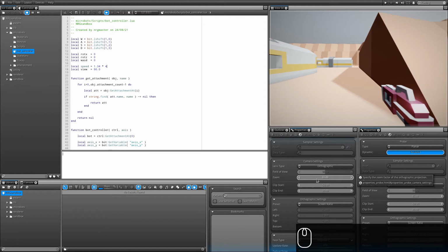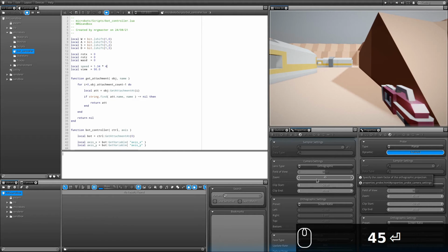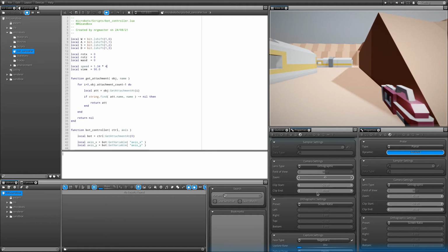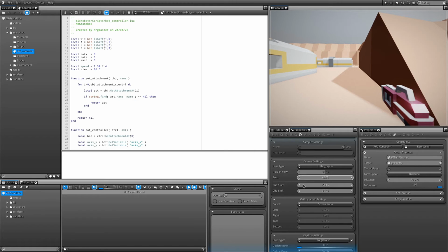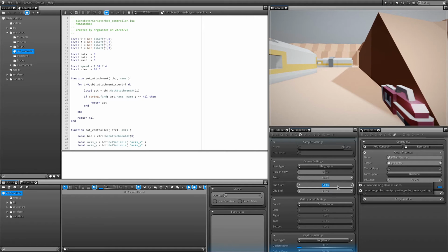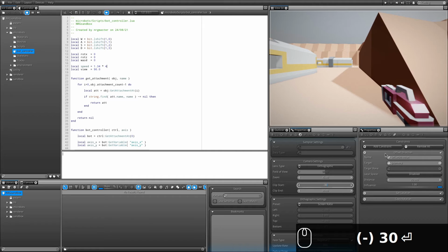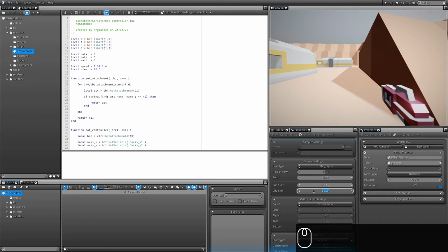Here I am going to set for my first probe that the zoom is at 45. And I go around and simply tweak and try to find the best combination. And here I am going to pull the constraint. So I've got the probe properties and the constraint of that probe. And as I was mentioning, I just walk around and simply try what is the best distance, what is the best zoom for probe 0, 1, and 2, and what is the best clip start and clip end. You can also adjust them to your liking as well. I feel that the values that I set here give a very good result. So we got zoom at 45, clip start minus 30 and 30.